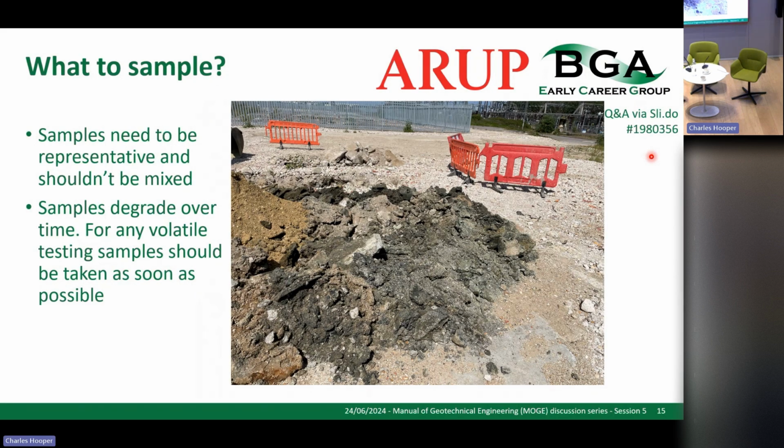And the other thing is holding time and material quality. Particularly volatiles get volatilized out of a sample very quickly in hot weather. And even for other things, we really want to have it as close to the in situ parameters as possible. So you should be taking them as quickly as you can to maintain it and then getting them into a cool box and off to the lab as quickly as possible. In this instance, this has been left in quite hot sun for several hours. You can see the outside is completely dried out. It would not give very good representative samples.